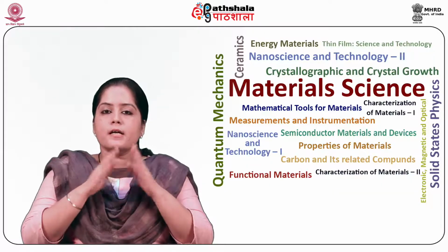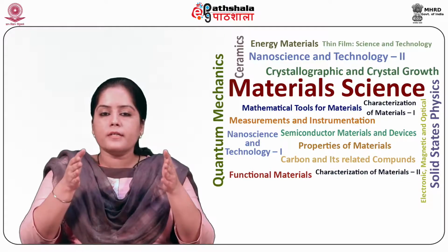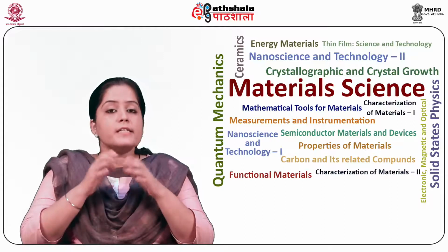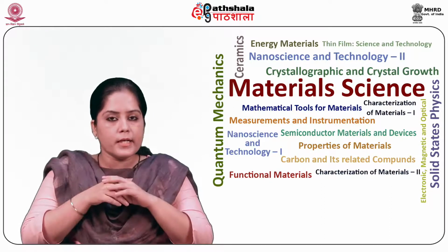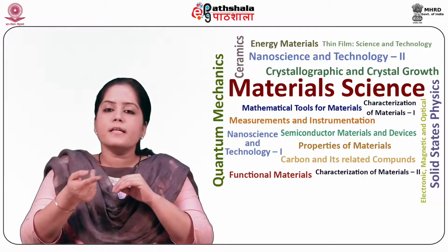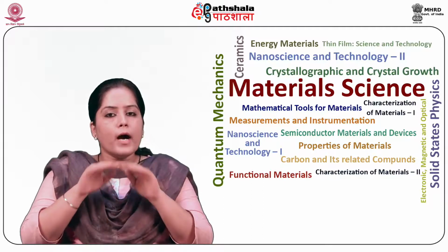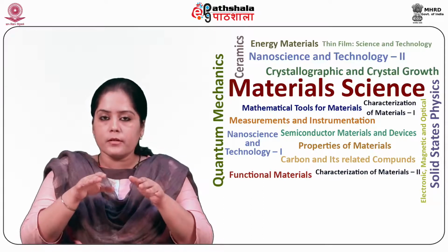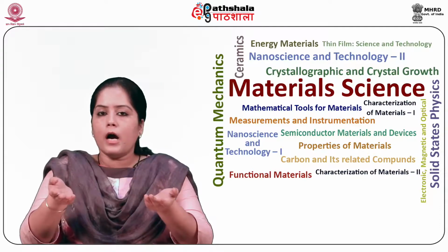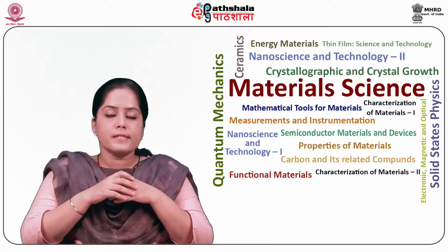Now let us discuss the applications. It has many important applications in material deposition. It has been used commercially to deposit the following films: oxides and nitrides of silicon, deposition for a wide range of applications including photonic structures, passivation, hard mask, etc. Second is the amorphous silicon.